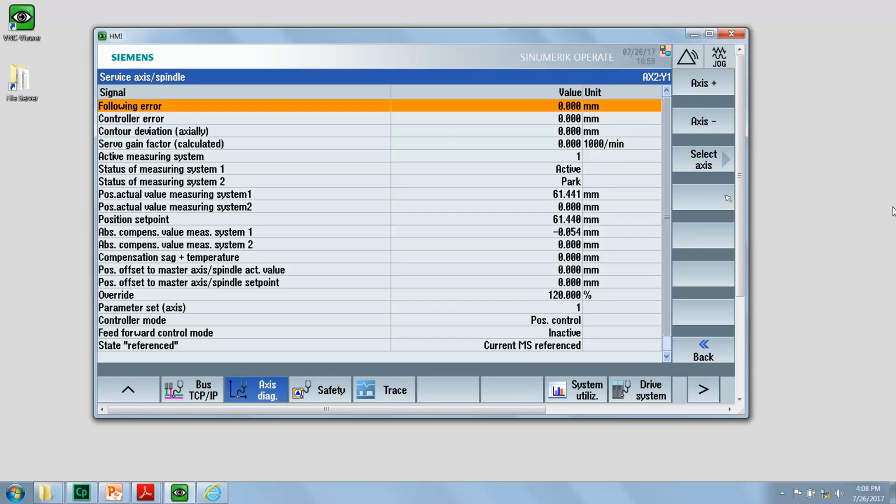So Alarm 4400 can be a bit of a hassle. And for machines roughly newer than 2016, starting with software 4.7, that's been resolved, where for almost all memory allocating machine data, it's no longer a concern. I've turned that off because there's a very, very small percentage of machines out there with latest and greatest software compared to the number of machines that are out there running with old software. So I wanted to demonstrate how old software works.